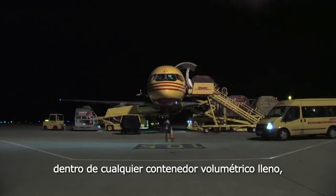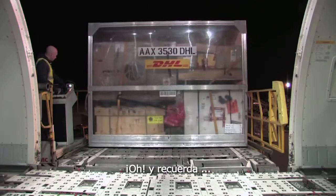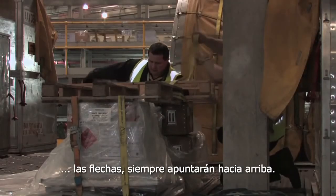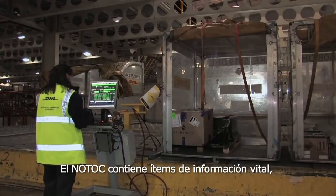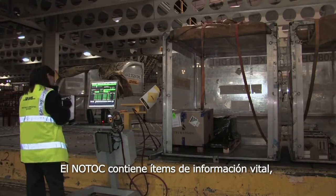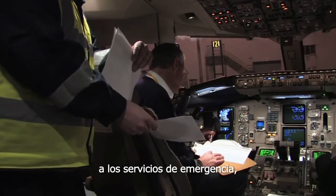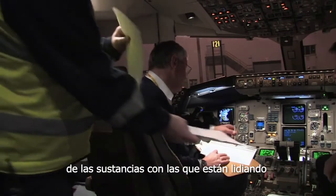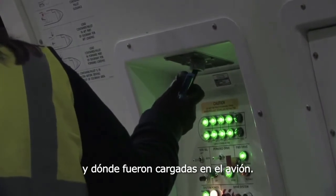That could either be within a volumetrically full ULD or compartment, or secured individually. Oh, and remember, the arrows always point up. The NOTOC contains several items of vital information. That's because if there is an incident, everyone involved, from the flight crew to the emergency services, are aware of the substances that they're dealing with and where they've been loaded on the aircraft.